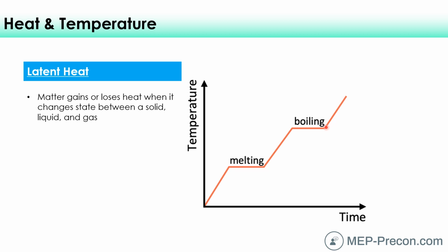And so that additional heat that's added to the liquid before it boils, that's called latent heat. Or specifically, it's called the heat of vaporization, and this is the heat of fusion, when that's the latent heat between a liquid and a solid state. And so that's important in refrigeration because we have a lot of phase changes happening, and within that phase change, there's a lot of energy that can be released.